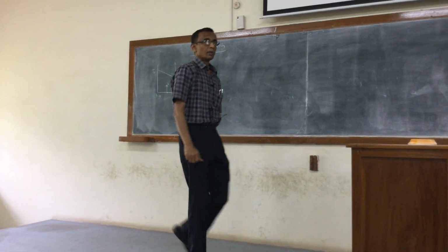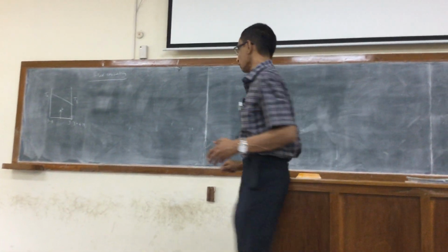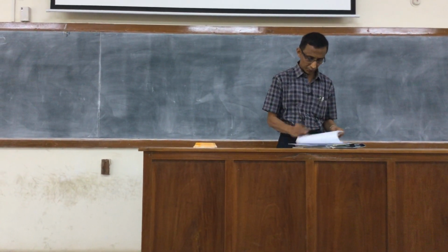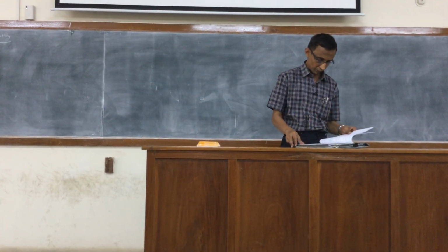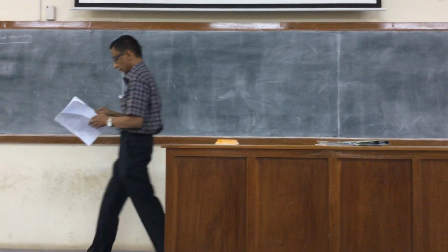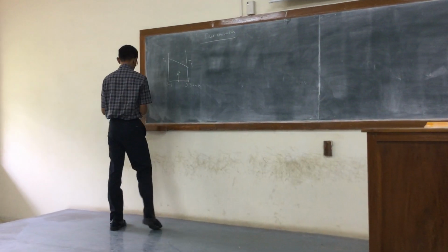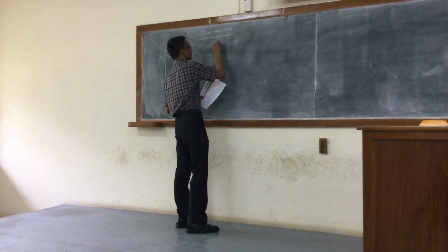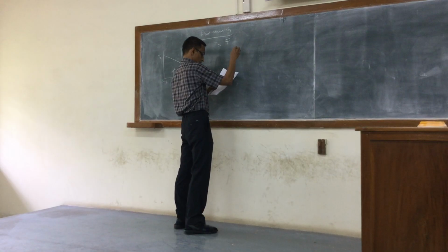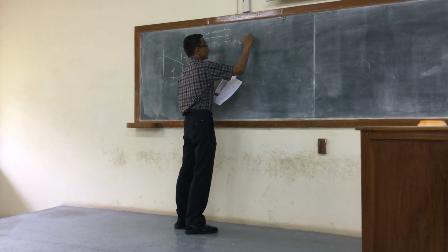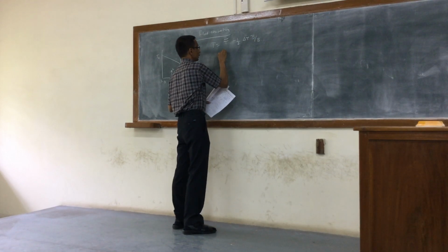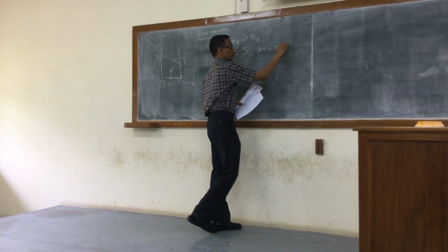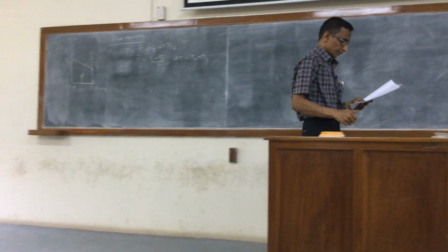So if you apply the momentum balance, the first step is actually, since the nature of the problem is such that the energy balance is effectively decoupled from the momentum balance, what we get here is a simple expression for the linear profile, which can be given as T equal to T bar minus half delta T y over b. The T bar is the average of the two temperatures, and delta T is T2 minus T1. This is the temperature profile.